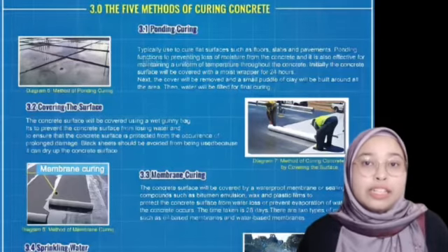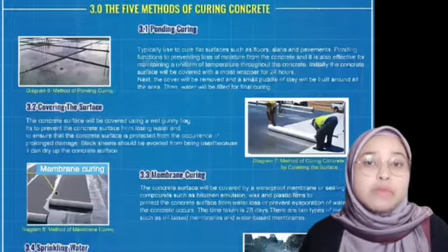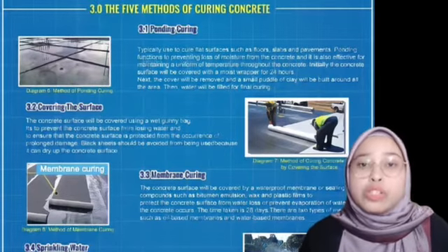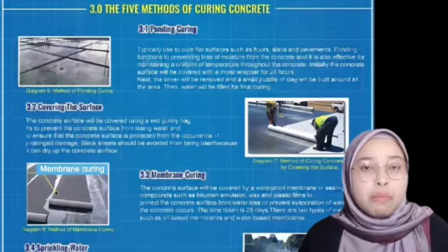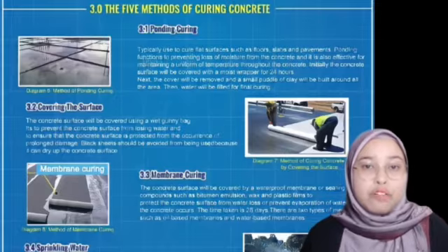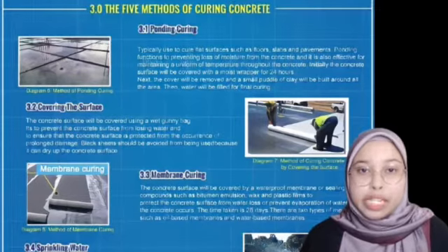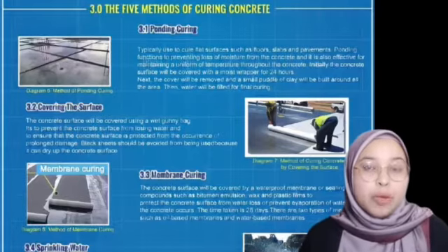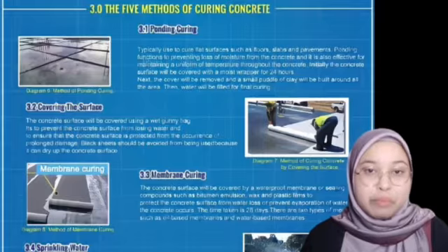In this method, a liquid material will be sprayed on the concrete surface and subsequently the material will solidify and form a membrane. This material can be applied with a brush or roller, and there are 2 types of membranes: oil-based membranes and water-based membranes. The most popular type of membrane used in this method is oil-based membranes.